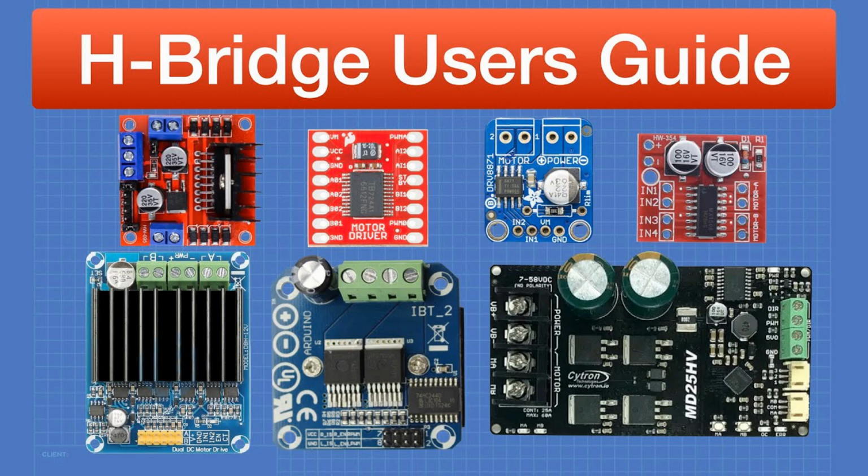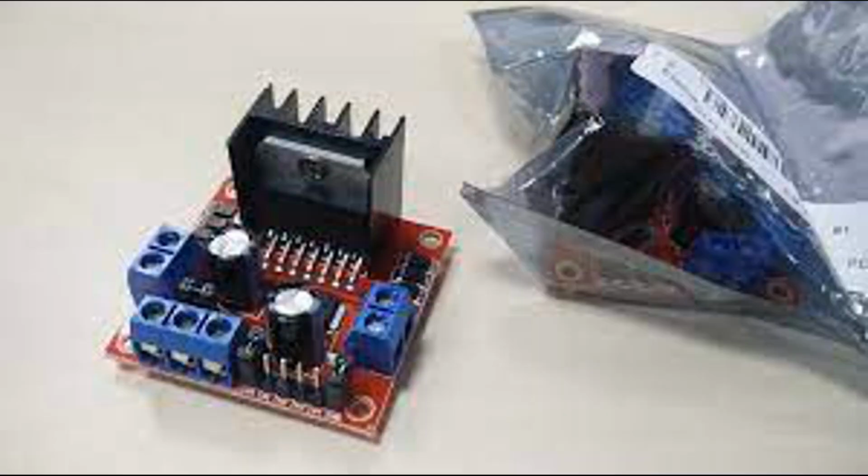7. Types of AC motors controlled by VFDs. Induction motors, the most common type of AC motor controlled by VFDs. They are rugged, reliable, and suitable for most general-purpose applications. Synchronous motors, used in applications requiring constant speed and high precision. VFDs can be used for controlling these motors as well, though they are typically more expensive and require more complex control systems. Permanent magnet synchronous motors, PMSMs, often used in applications requiring high efficiency and low maintenance, such as in electric vehicles and robotics.